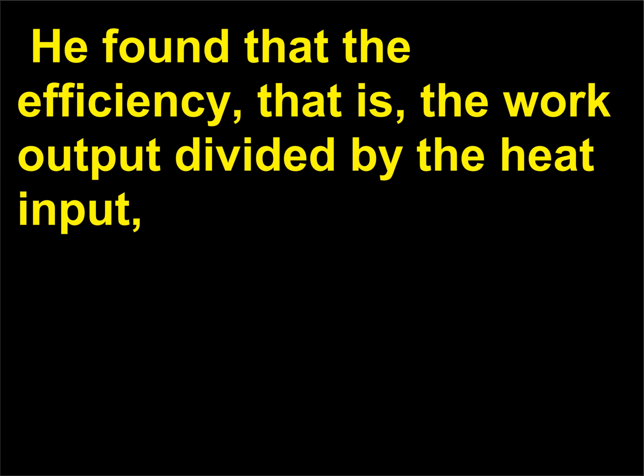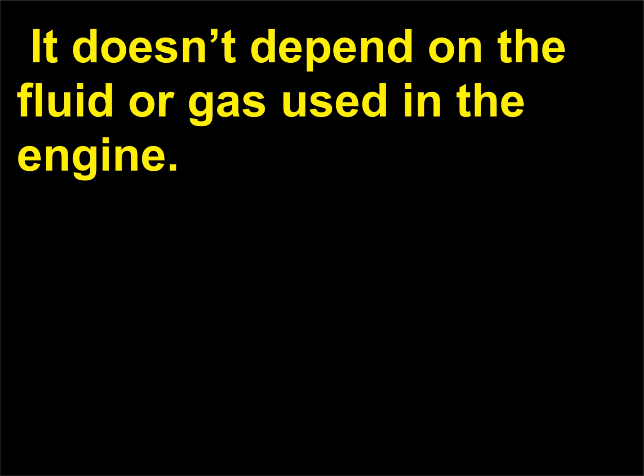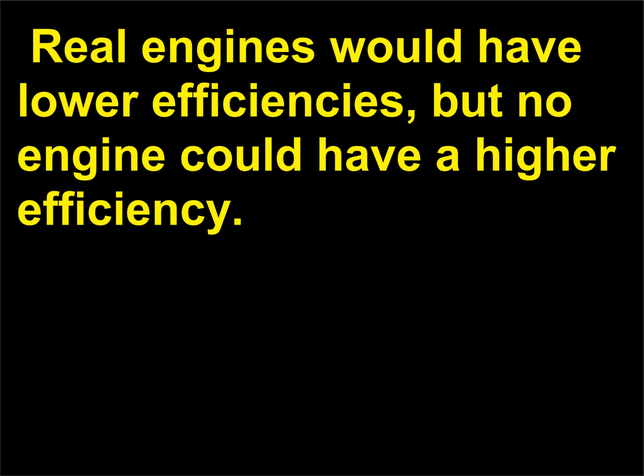He found that the efficiency, that is, the work output divided by the heat input, depended only on the temperatures at which heat enters and leaves the system, or efficiency equals 1 minus T_cold/T_hot. It doesn't depend on the fluid or gas used in the engine. Real engines would have lower efficiencies, but no engine could have a higher efficiency.